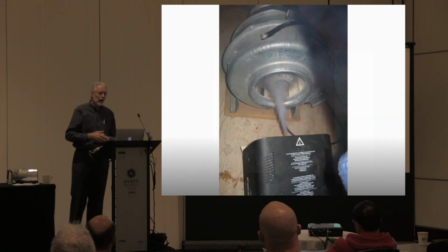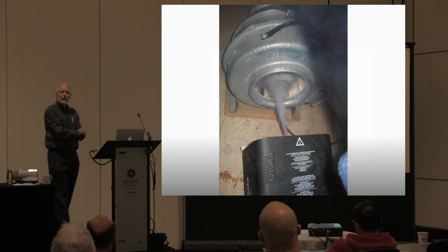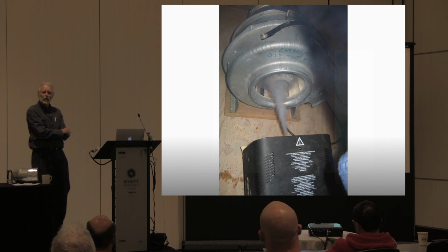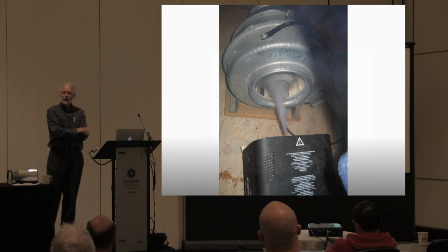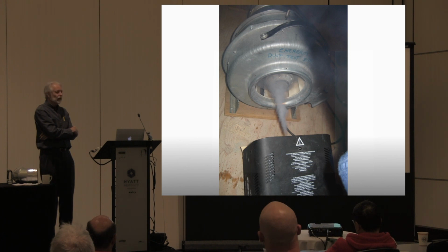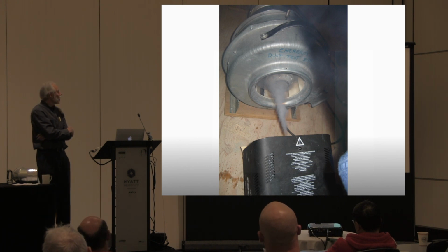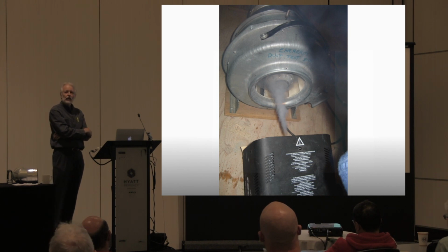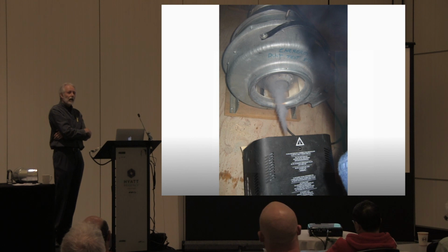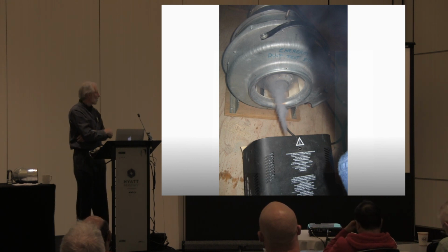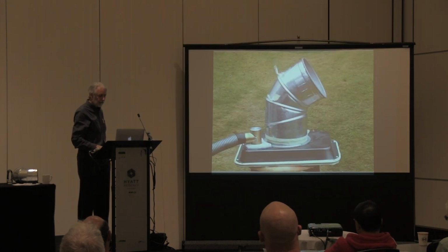About 10 years ago, we bought a theatrical smoke generator because we were using it for testing ventilation systems. We have a hell of a lot of fun with that thing. But we're too stupid to know what to do with it, so it sat on the shelf for 5 years. And finally, we ended up with some bad systems. We took it out and actually used it on a house, and it was just a wonderful, wonderful training aid. So what you do is you take a ventilation system, you pressurize it, close up the openings, you put smoke into it, and absolutely amazing what you can learn from it. It's just a super tool.